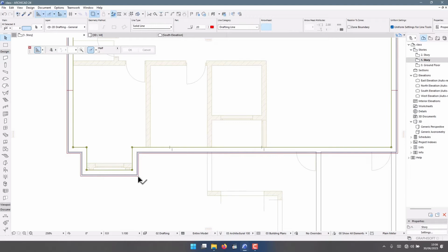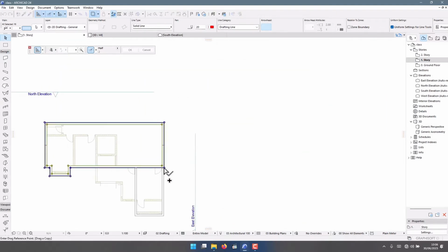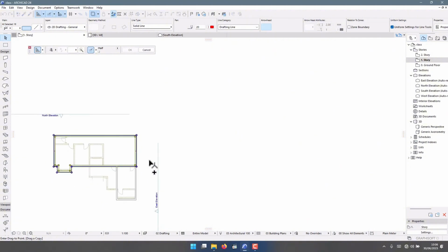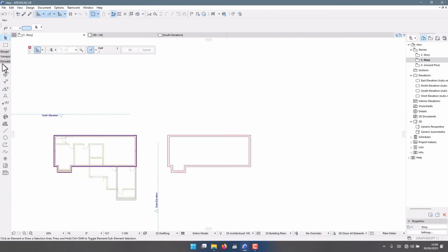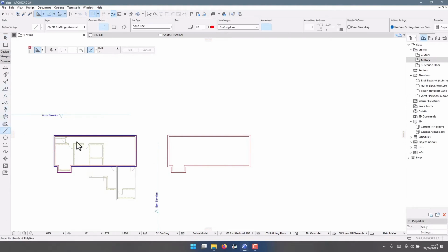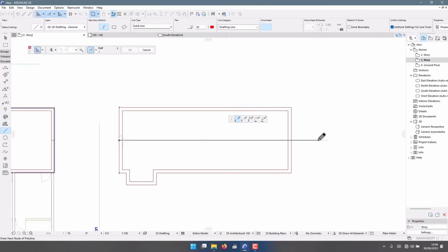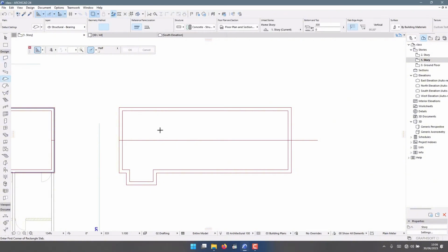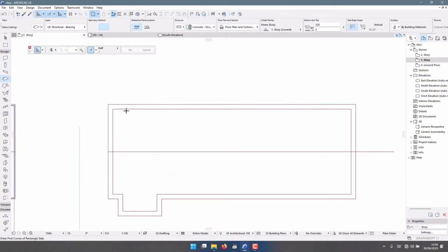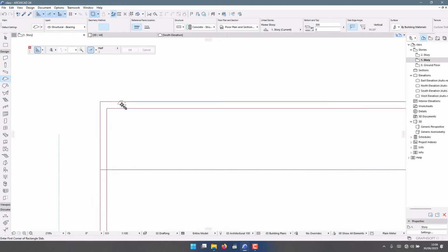select this line and press Control Shift plus D and copy it outside, so we are dragging it outside by 20,000. Okay, then this is better than doing it manual. We can close it. We wanted to close it at the center here, and we do it like this. So then I go to the slab option or slab tool, and I do this. You can use this here.